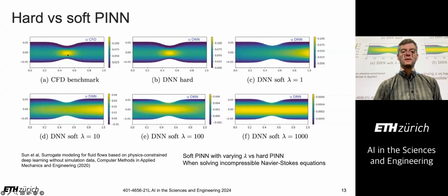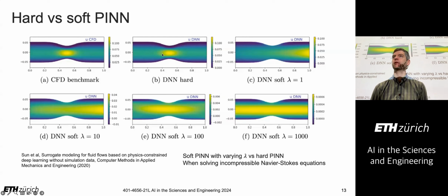So it turns out when they were testing different PINNs, so this is the ground truth solution. When they were testing different standard PINNs, they couldn't find any value of lambda, so when they were using both terms in the loss function, to converge onto the solution, probably because there's quite a big competition between the boundary loss and the physics loss. But when they use the hard constraints here, then they were actually able to converge the PINN. So this definitely helped for this particular example.